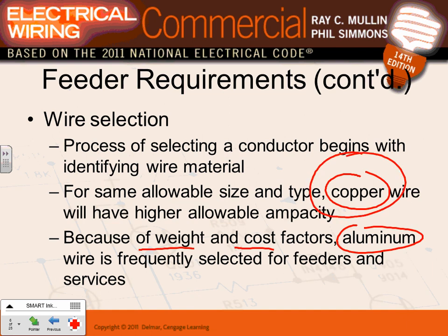Copper. Why copper? Less maintenance, for the most part, and it carries more current with smaller conductors. It's more expensive, but you're investing in the future, the next 25 to 30 years of your company. But a lot of contractors will be pushing aluminum on you.